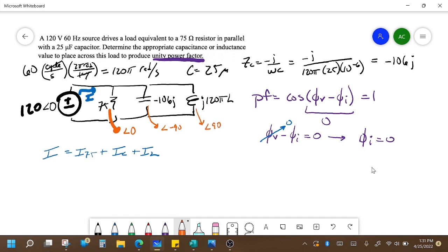And so what happens is, if I look at just the resistor, it's not going to affect anybody because this angle is 0. It can't offset anything because it has no angle with which it has the power to offset any signal. Basically, what I'm trying to say is if you have a purely resistive AC circuit, all of your output signals are going to have the same phase as your input signals because resistors don't change the phase. That's what I'm trying to say. Capacitors and inductors are the guys who change the phase.